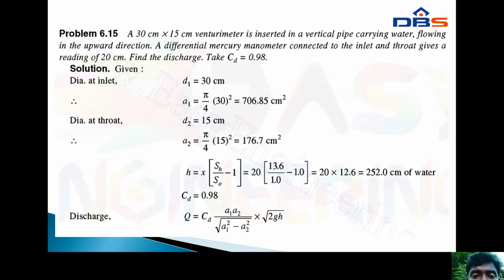Next, this is another problem. A 30 centimeter and 15 centimeter Venturi meter is inserted in a vertical pipe carrying water flowing in the upward direction.